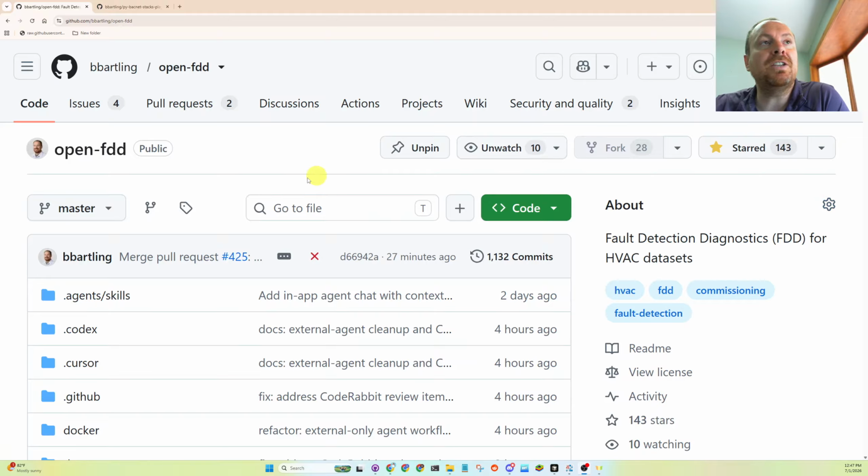So, like Open-FDD, when it runs in the field, in the operations technology land, it'll come up as a BACnet device, and the idea will be that it'll display the number of faults that it's detected in the HVAC system, and maybe we could even show some weather data from the web to the control system network. So we can do some cool things as a BACnet server, but I'm still troubleshooting why it's not showing up as a BACnet device.